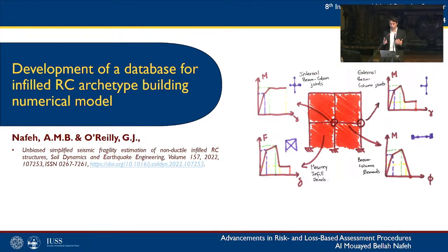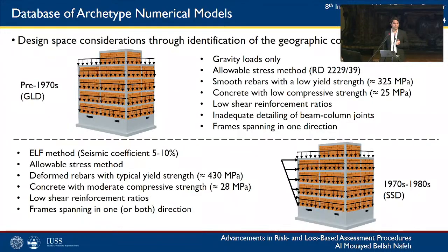But first, assessing the seismic performance or validating code-based procedures requires analyses performed on building models that are considered widely representative of the building class under investigation. These models are generally referred to as archetypes, and so as a first effort, we dealt with the development of a database that includes archetypes of infilled RC numerical models.